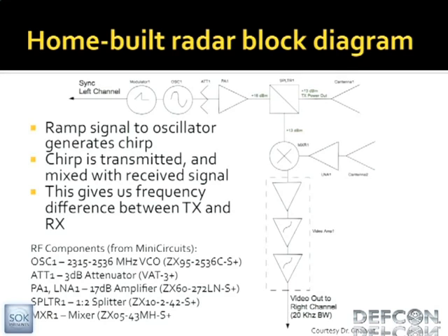And the original system for this used a sound card. I've actually changed that a little bit since then, but that's what's cool about this: you can literally build something like this and record your radar data with your sound card and just process it on the computer. You record with Audacity and then process it in MATLAB. That was how the original system worked.